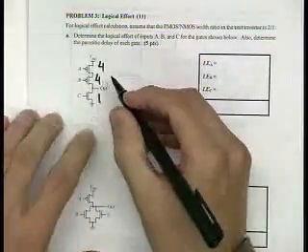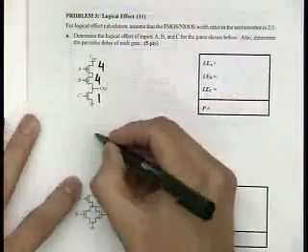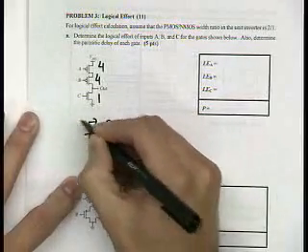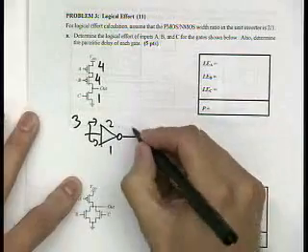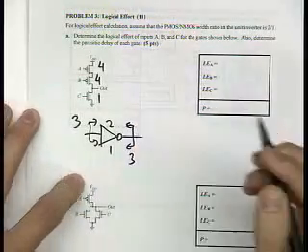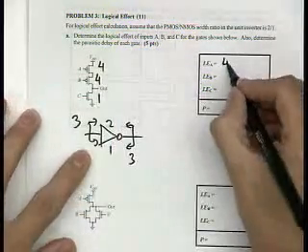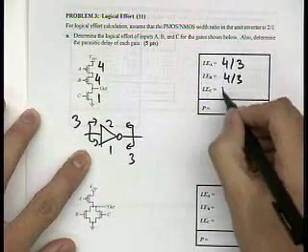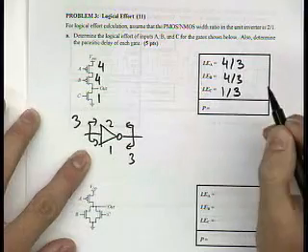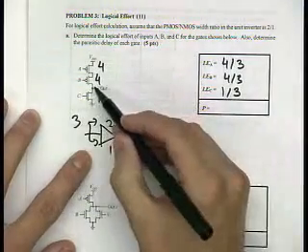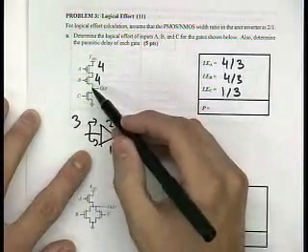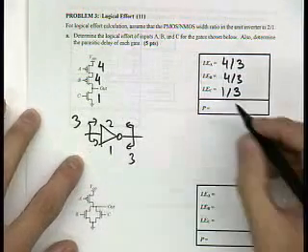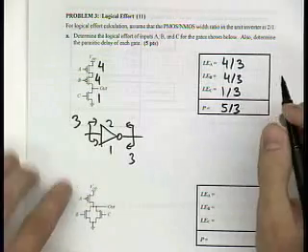You know that the inverter is 2 to 1, so this is 3 over here. For the parasitic delay purpose, it's also 3. So logical effort of inputs A and B is 4 over 3. Input C is 1/3. And finally, parasitic delay, you sum up all these capacitances at the output node, divide by the capacitance looking into an inverter. So you end up with 5 over 3 here.